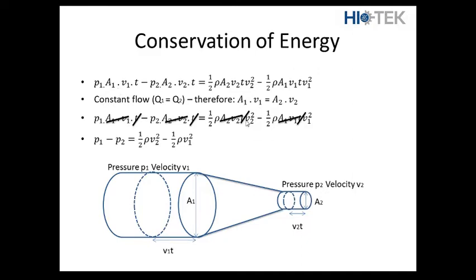And this is crossed out prematurely, but basically if we take that previous pressure version of E that we calculated, we can make it equal to the kinetic energy version of E as we calculated previously, two sides of the equation. And we've said it's an ideal fluid with constant flow, so we have Q1 equals Q2. Q equals the area times the velocity, is your flow rate.